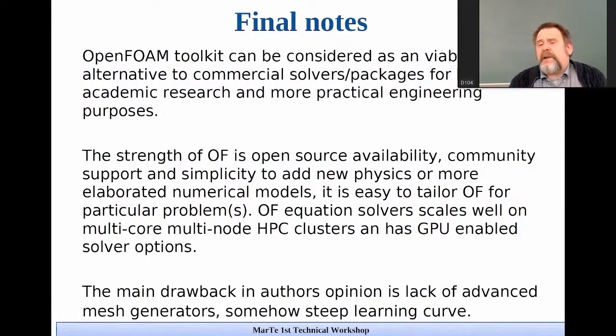The main drawback is that we have no advanced mesh generators. Post-processing is more or less organized well, but I would like to see better mesh generation for pre-processing. Somewhat steep learning curve, and something which I didn't mention, it is constant change. OpenFOAM, as open software, evolves.